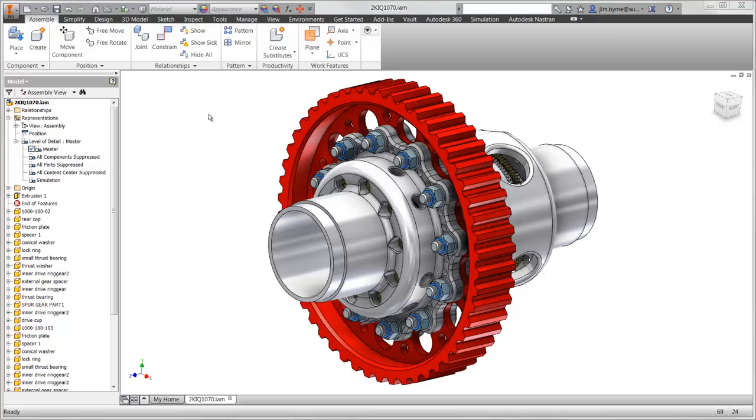in the assembly. There are a couple approaches that can be taken to set this analysis up. First, we can analyze the bolts as they are and gain some knowledge of the stresses on each of them. The second approach is the use of connectors. Connectors act as one-beam elements, which solve extremely fast, and they also provide additional information for the shear and axial force. Now that we know the setup we're going to use, we can hide the other parts in the assembly,